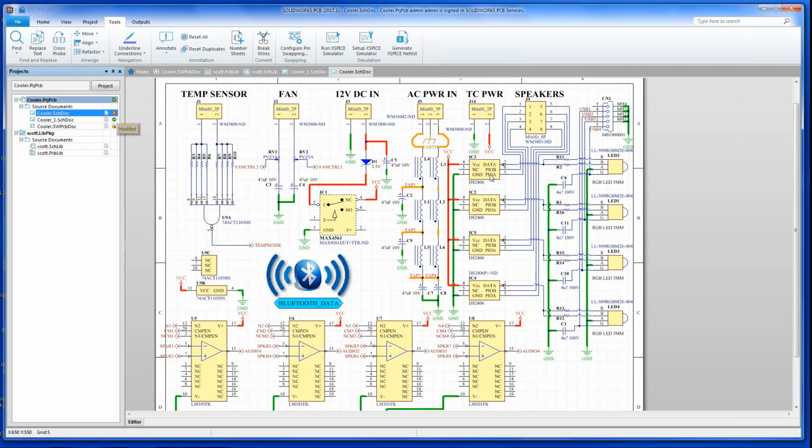The tools that are available in the schematic capture, these are sort of the higher level tools where you do your annotation. You can have full pin swapping capabilities. You can configure logic gates. You can configure resistor packs. You can configure any component that you wish to have pin swappability. And then in the PCB, you can automatically pin swap it, or you can selectively pin swap it to have a better route configuration. The SPICE simulation that we provide is an XSPICE output, and you attach the models to your symbols, and you can generate the XSPICE simulation files.